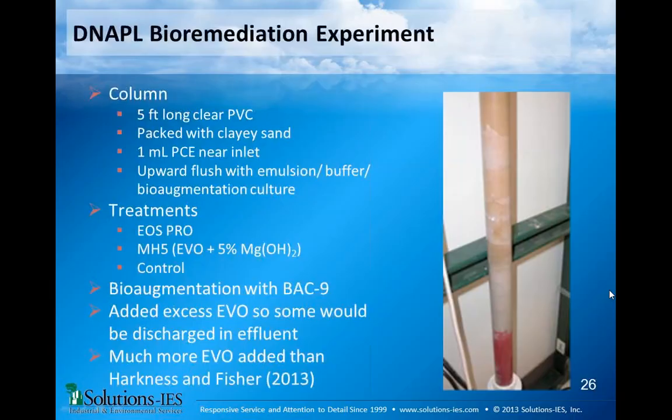So they'll inject a concentrated pulse, then chase it with water, then another concentrated pulse. Sometimes they use chemical inhibitors, citric acid, low pH to inhibit the growth around the well. Sometimes they just have to go clean the well once a week or every 2 weeks. There are things that work, but a lot of them are relatively labor intensive.